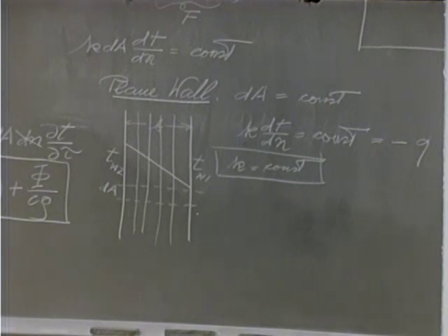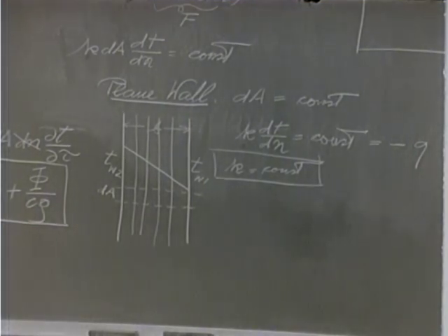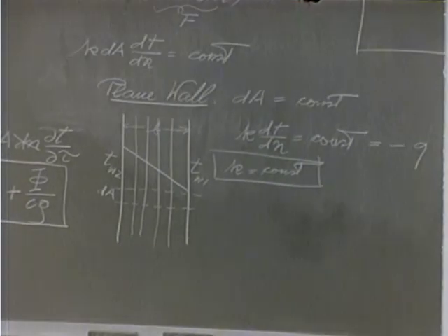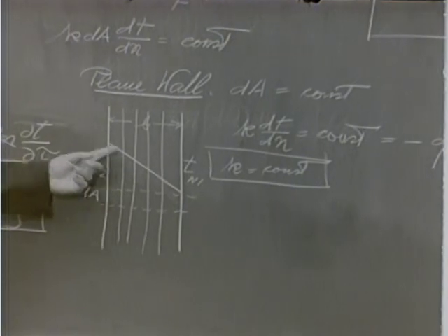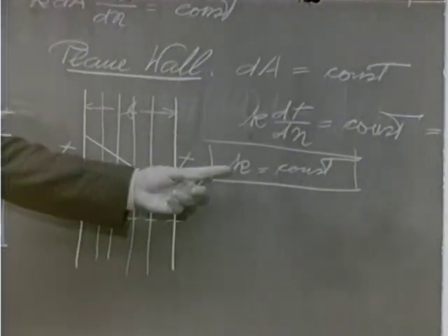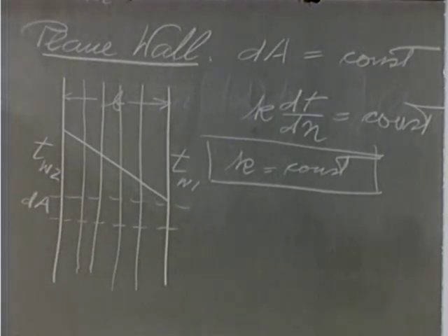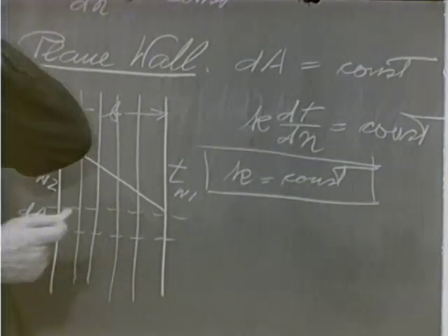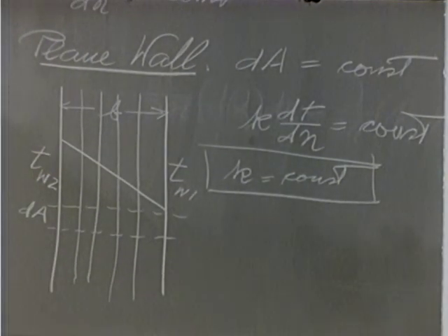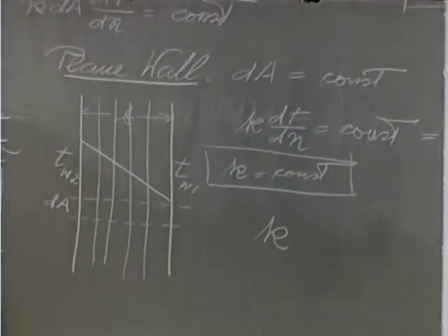We can consider that we have the linear temperature drop only for a material for which the k is constant. We have seen in diagrams that the k in general depends on temperature. Now this would mean that if we have large temperature variations, so that this k variation with temperature is large, we would not get a linear decrease. Well, maybe we can just get then to the form of the equation with which we started out, to close our circle. Now, obviously, we can then write k.